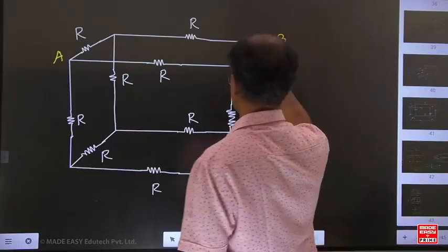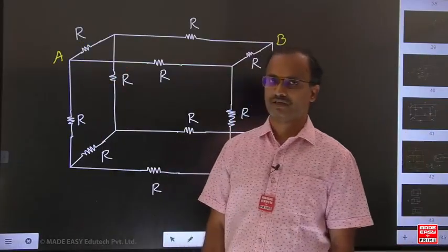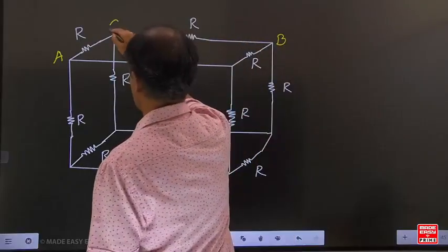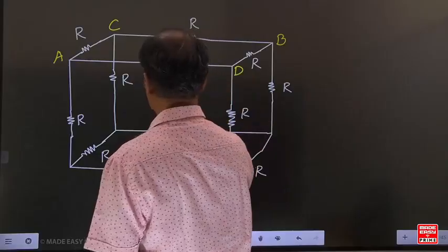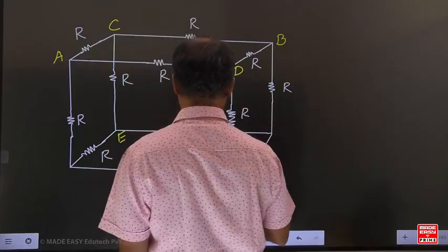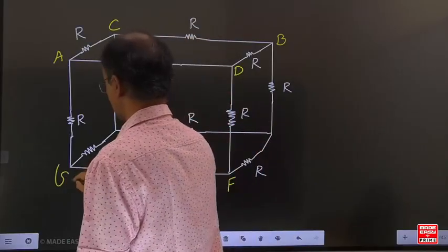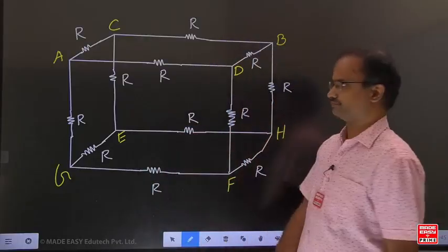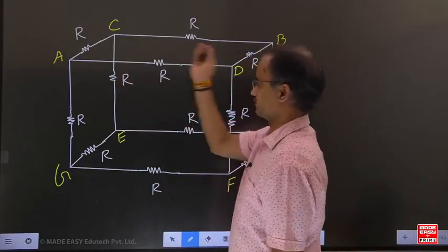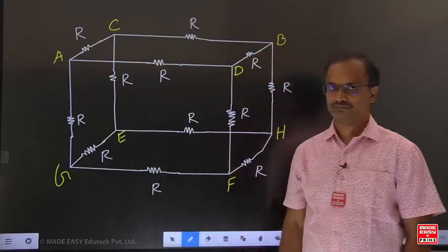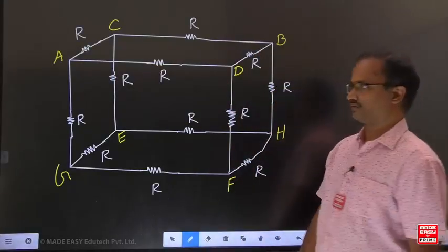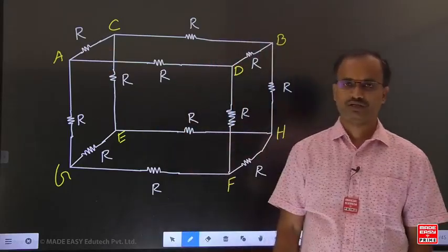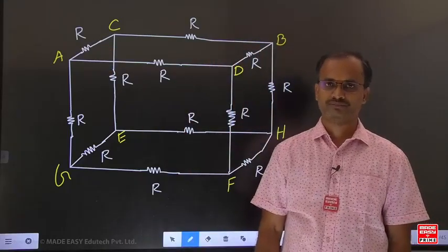Now for this example, what is the requirement? The equivalent resistance with respect to A and B. Now give any names here. Give the names as C, D. Can I indicate like this? Now concentrate on these A, B, C, D points. Like either R and R. Now indirectly the balanced bridge condition is satisfied.